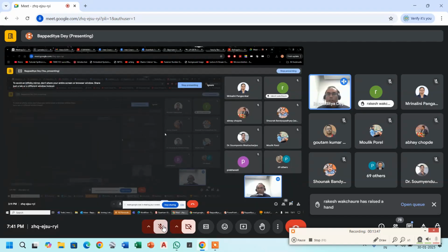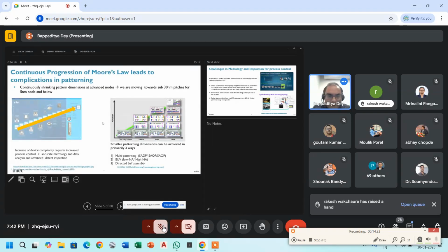To understand the complexity of this tool: it is generating the UV light, the purple light you have seen. To generate this light, which is responsible for printing the device, you need to hit 50,000 droplets per second. That means there is a droplet of a chemical, and it has to be hit by the light source. 50,000 droplets have to be generated per second to create this source. So you can imagine how complex this process is going to be.